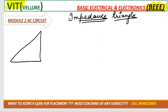Yes or no? In the base we'll always take the resistor resistance. In the perpendicular we'll always take the inductor resistance, that is XL, or the capacitor resistance, that is XC, or the combination of these two. The hypotenuse would be Z. Z means impedance, right? And the angle between them is always phi.